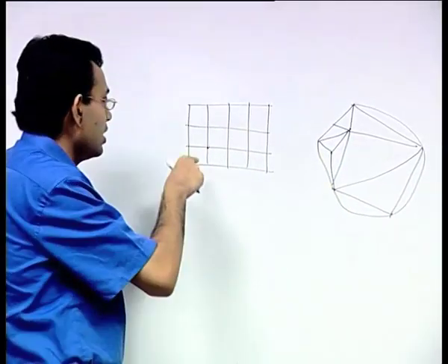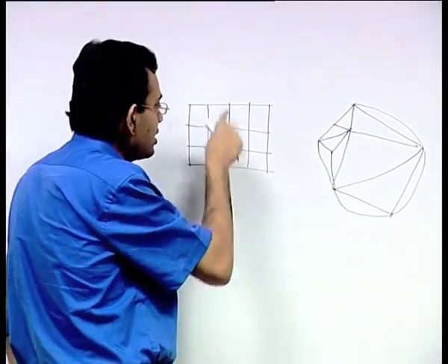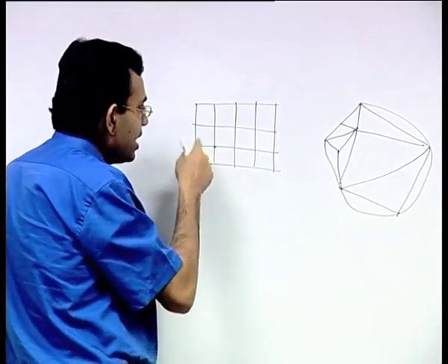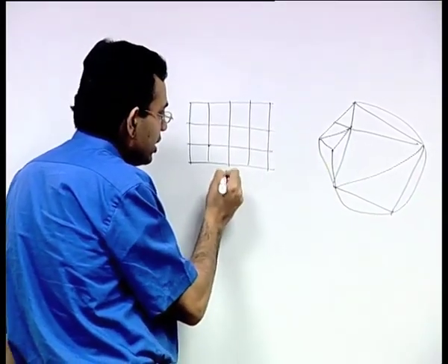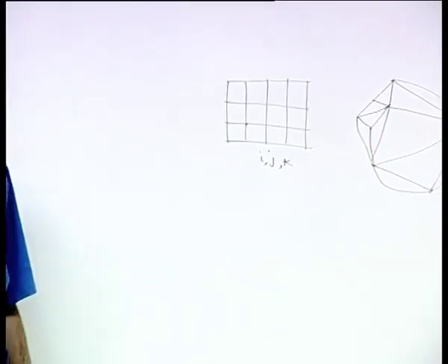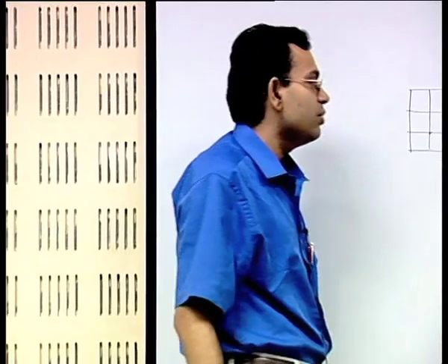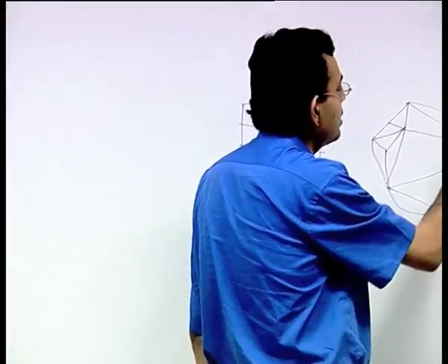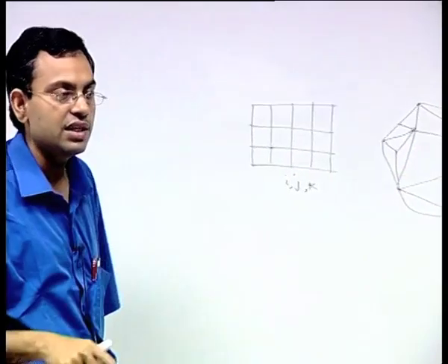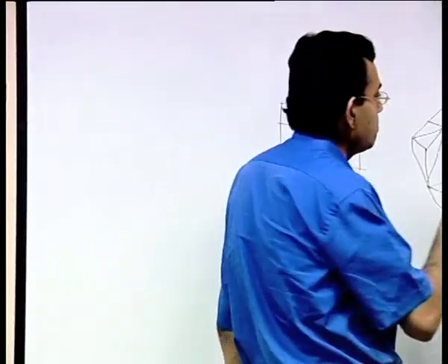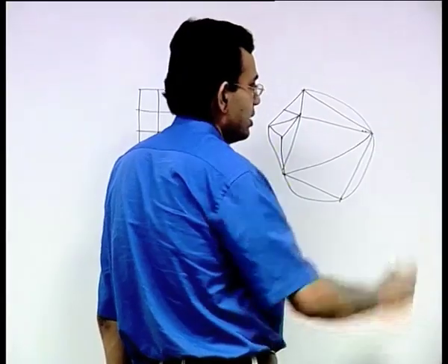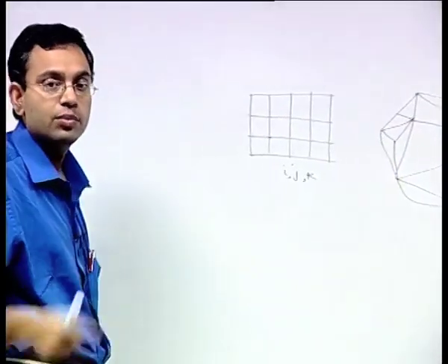Because of such a structured layout, for a structured grid you can express the grid locations or coordinates using indices i, j, k depending on the dimensionality. Whereas in an unstructured mesh you have to explicitly specify the coordinates of the vertices, without referring to grid line orientations i, j and k, and then establish suitable connectivities.